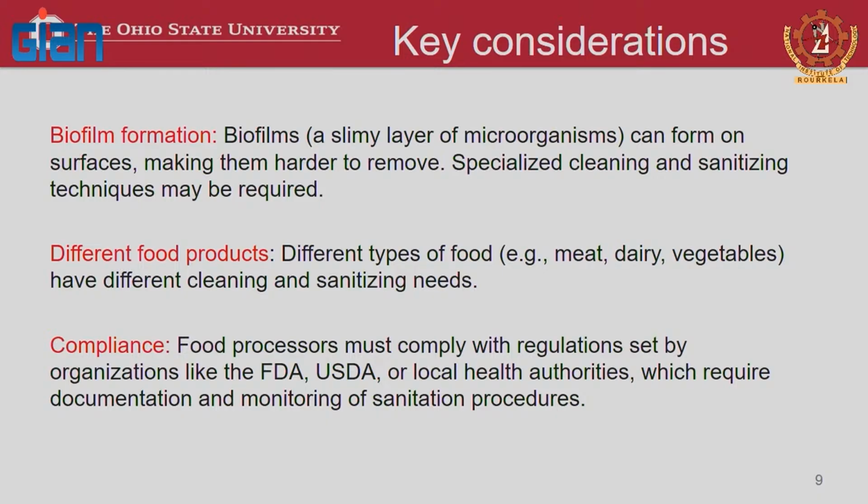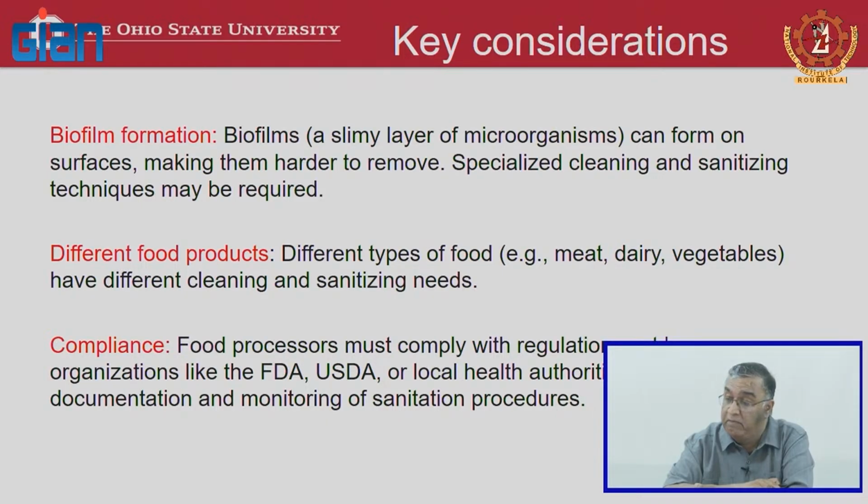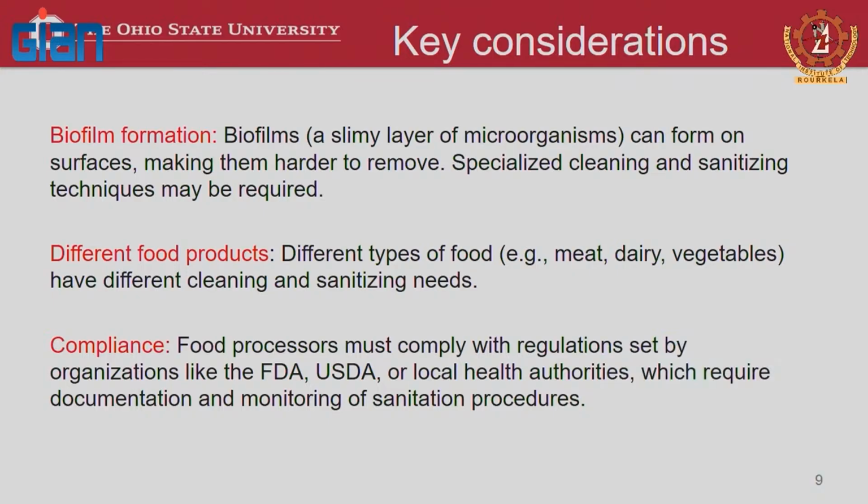Yesterday we talked about biofilms. Biofilms can form on the surface. Basically, it is a small thin layer of microorganisms, and they are much more difficult to remove compared to even some of the foulant types, because microorganisms deposit in multiple layers and form a colony, and then they are much more active, and it requires much greater effort. So, you need to have specialized cleaning and sanitation techniques.